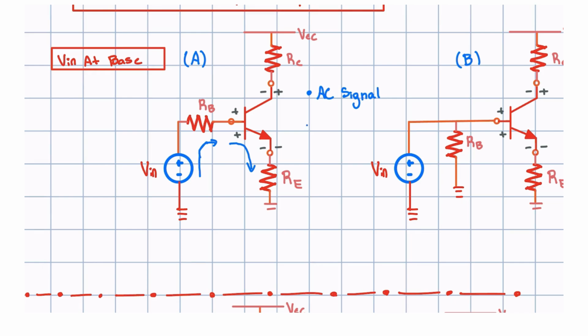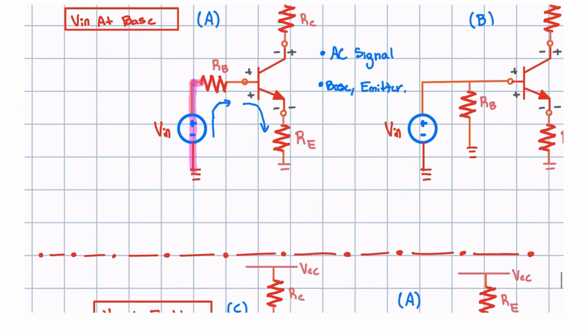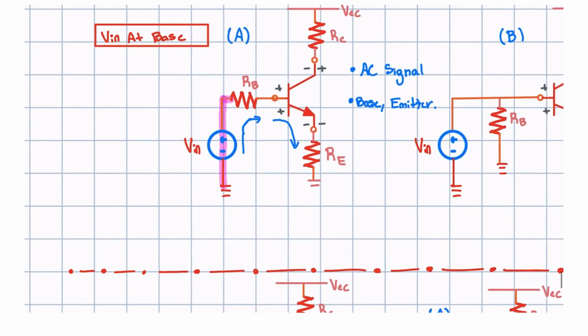So the second thing we have to pay attention to is the base and emitter. As we follow this current path, we start from ground and go up until we touch the resistance at the base, this RB. When we're writing this input impedance, typically denoted as Rin, we add this resistance, and it remains unchanged. There's nothing special about it. Great, we just keep moving forward.